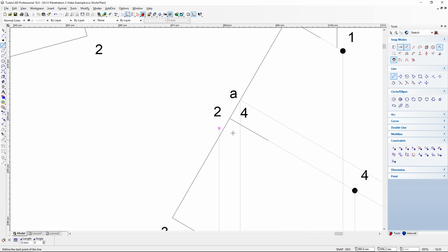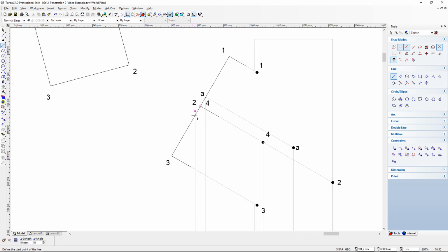So to 2, 3, there is 2 and there is 3, so that's the side that it hits, and I am going to shorten that line, and now again with that slant of 330 degrees I'm going to draw a light construction line. Now the length we will determine just now, there's the angle of 330 degrees, and now I'm going to just cut away the excess